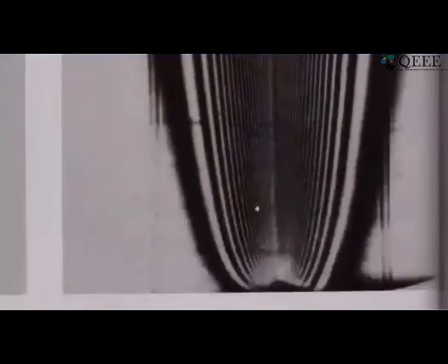So if you are at the lower edge, you can see that the number of these fringes is much smaller. So you can see here this is the plate in the middle, and you can count these, and these are fewer in number, but as we went up, their number increased, which meant that you have higher and higher temperatures coming up at the top of the plate, and that is what you would expect in a constant heat flux case, that the isotherms would have a slightly different shape and size and location than what we saw in the isothermal case.